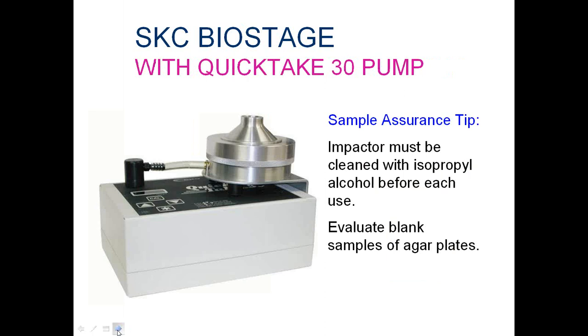The QuickTake 30 sampler pump has a mounting bracket to attach the biostage sampler for easy transport. Also note the valuable sample assurance tip shown on the slide. Be sure to clean the impactor with isopropyl alcohol before each use and evaluate blank samples of your agar plates.